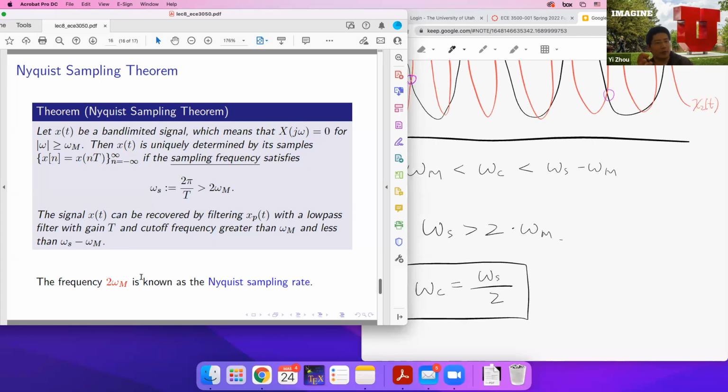And there exist other more efficient sampling approaches. In the forward process, in the sampling process, we look at other classes of signals, not just band limited signals. A very interesting class of signals is sparse signals. All the signals that we encounter in practice, images, audio signals, have sparse representations in some domain, Fourier domain or other domain.